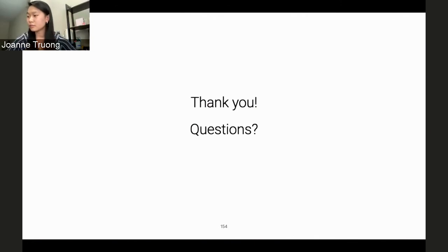Yeah, so there are multiple ways to answer this question. One, yes, traditional classical approaches can be incorporated within these learning pipelines, but the benefit of using reinforcement learning is just that the agents can learn to achieve a much higher performance than traditional approaches. So with traditional approaches, you map the environment, which means that first you would have to have access to the real world environment and create this map before the robot can navigate in it. Whereas in reinforcement learning, it's learning in simulation on other houses, and then you can deploy it into a new environment without having to do this pre-mapping stage.